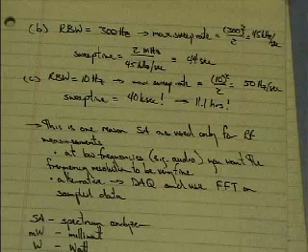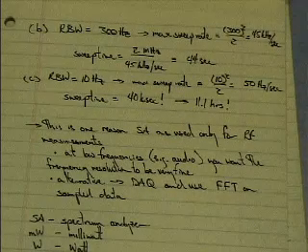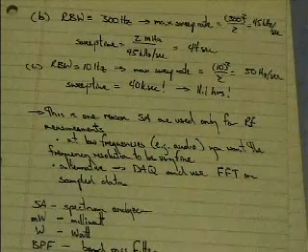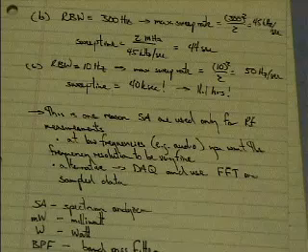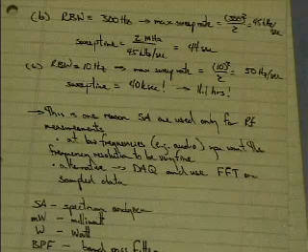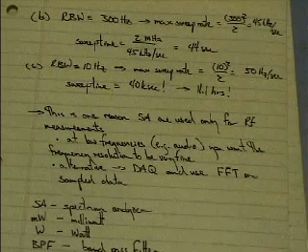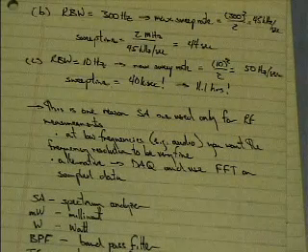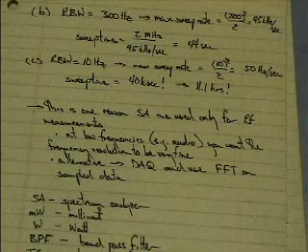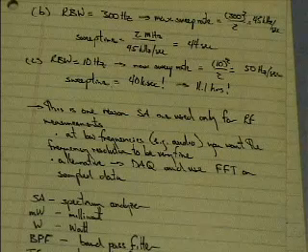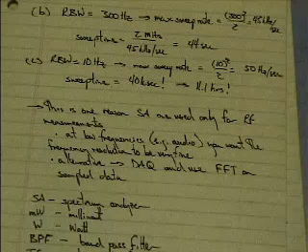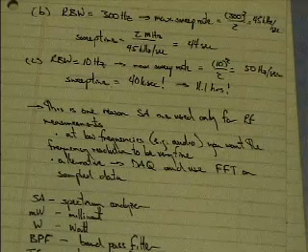So at low frequencies, what we tend to do is use a data acquisition card, a DAC, sample the data, collect it, perform a fast version of the discrete Fourier transform, the FFT, on our data, and then look at the spectrum. This is what we did last semester in 171. You may have done this in a signal processing course or something like that.